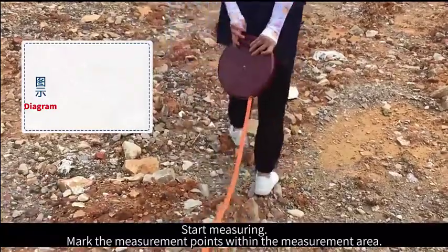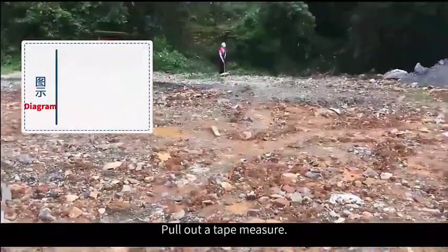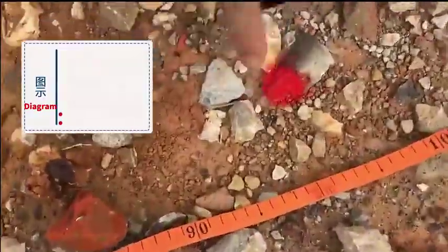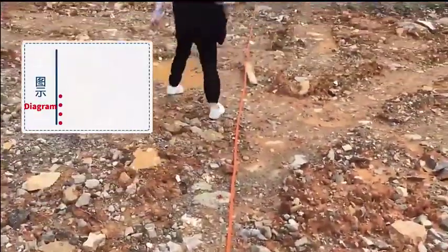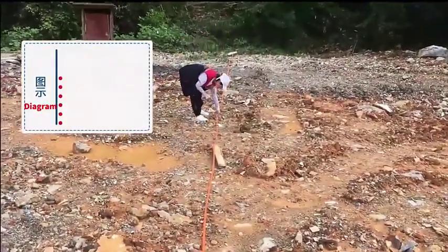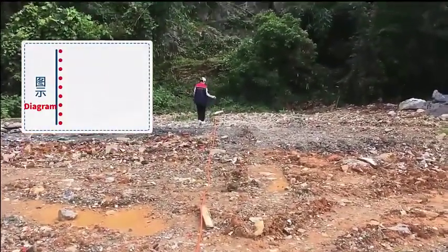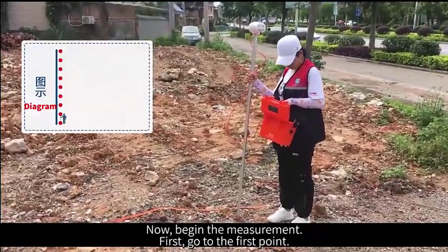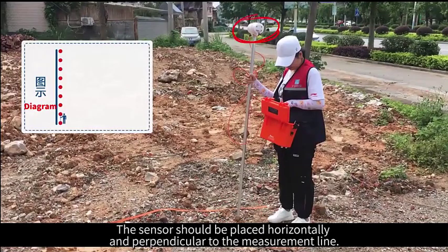Start measuring. Mark the measurement points within the measurement area. Pull out a tape measure. Mark each measurement point. Now, begin the measurement. First, go to the first point. The sensor pole should touch the ground. The sensor should be placed horizontally and perpendicular to the measurement line.